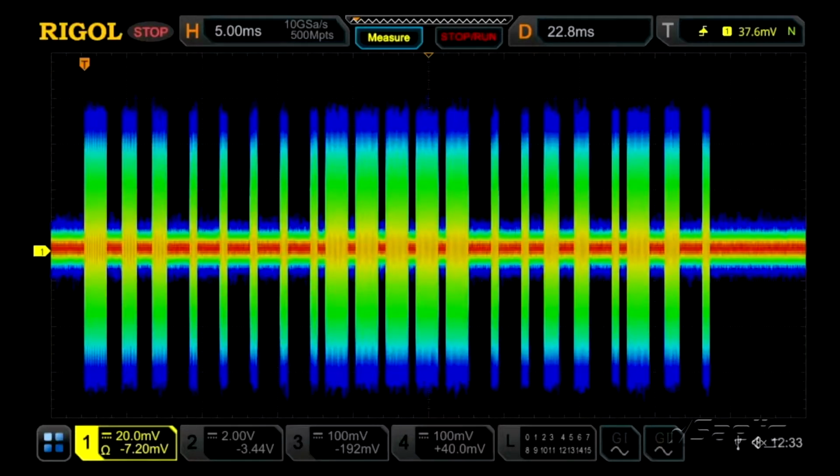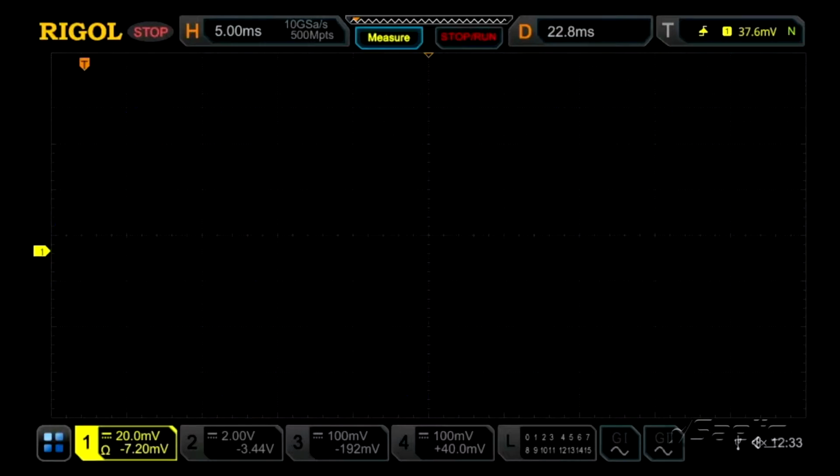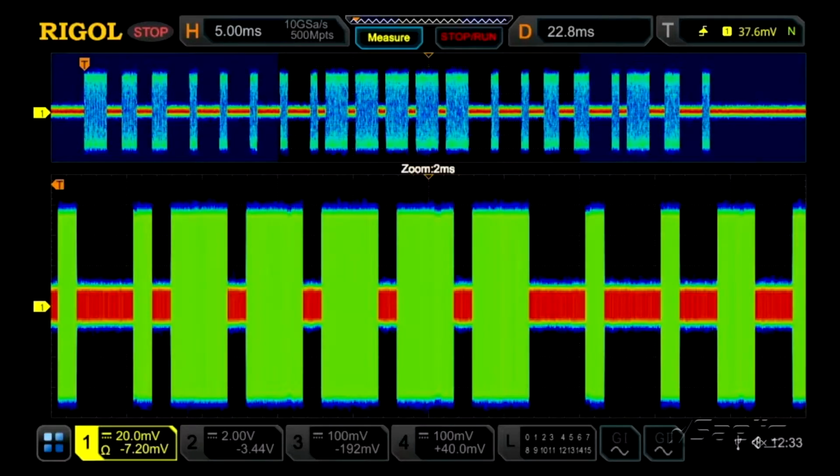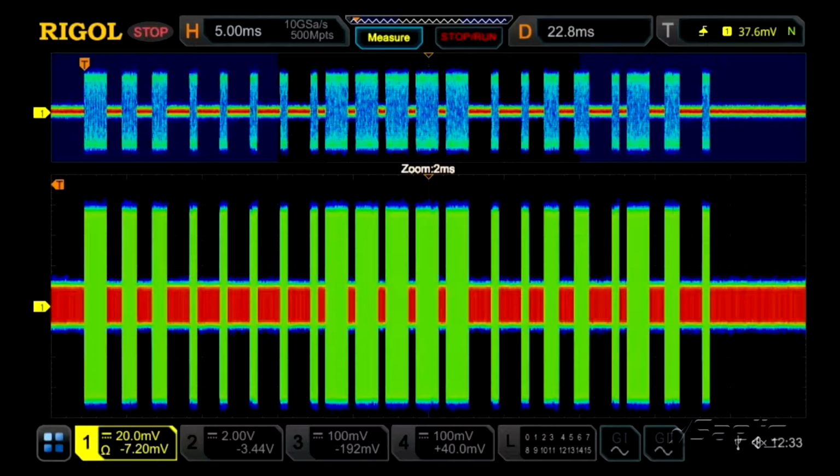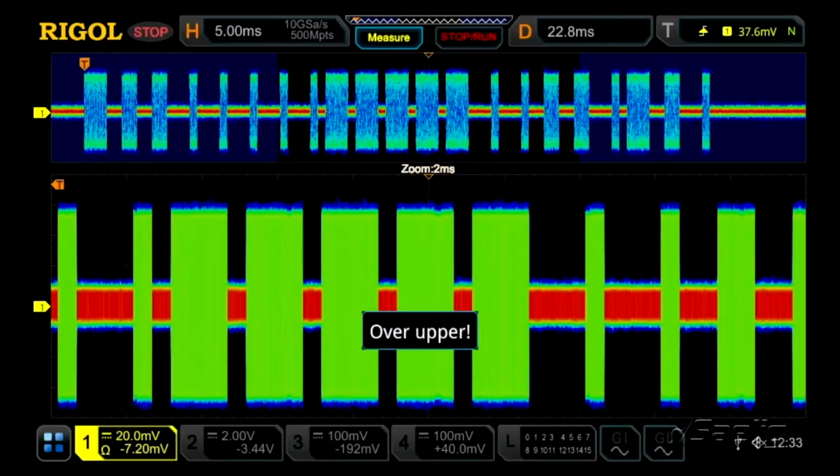We can see that we go out a little bit. We can see we have 5 milliseconds per division and 10 divisions. We have 50 milliseconds of data at a full 10 gigasamples. So that really allows us to see this entire RF pulse from this garage door remote here, so we can look closely at that. And then, of course, we can zoom in and look at all the detail because we have 20x oversampling on all those pieces.